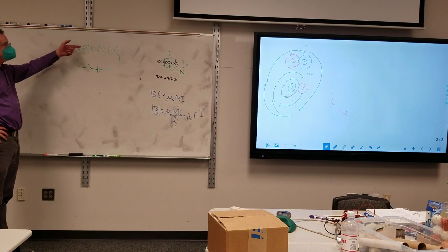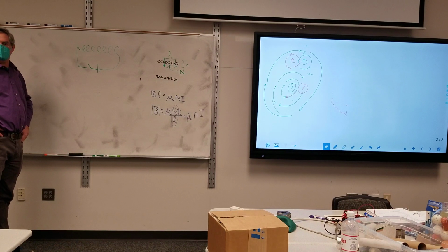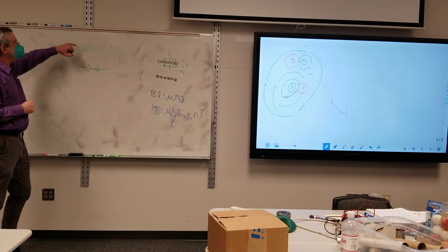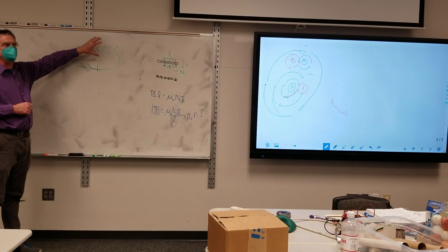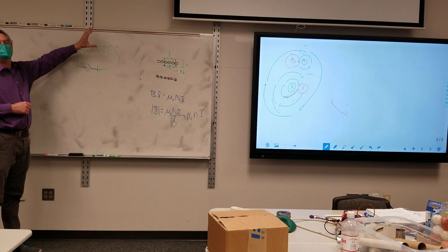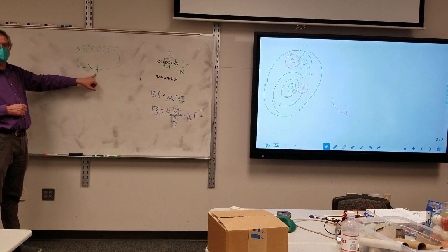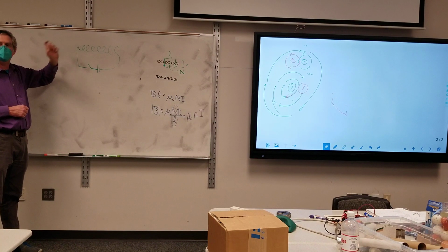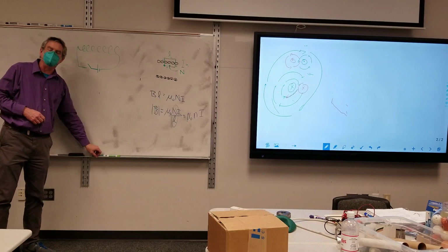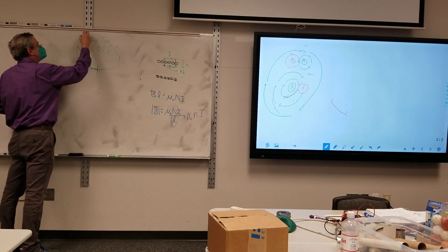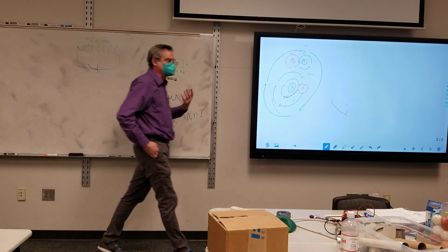All right. So I have a magnetic field that's produced. So if I have a magnetic field that's produced, what else is happening? Pardon? Yes. Because my magnetic field goes from 0 to something, I have a change in the magnetic field. Therefore, I have a change in the magnetic flux. Therefore, I have an induced current. So there's a secondary current that runs along this. There's the primary current coming from the power supply, and then the secondary current created because of the solenoid. Or at this point, it's not called a solenoid anymore, really. It's called an inductor. A solenoid is an inductor, just with higher resistance.